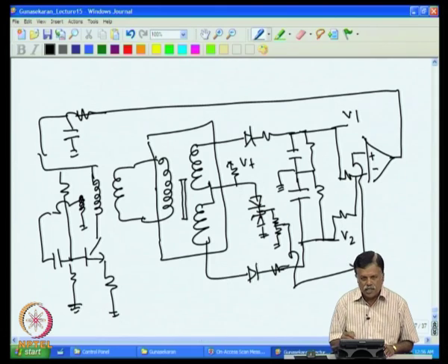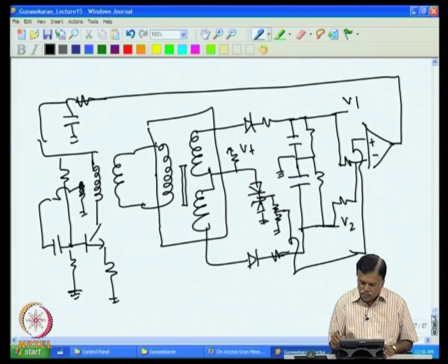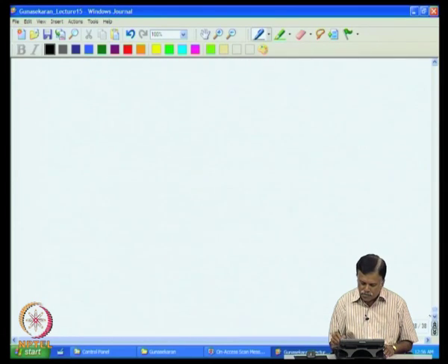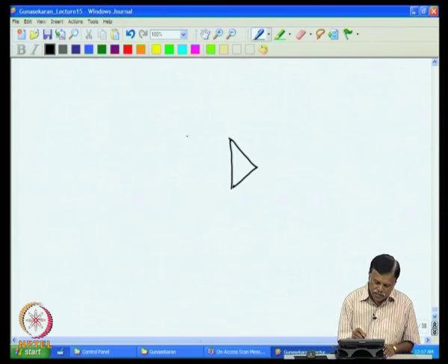the LVDT is to be energized first. Now, the V1 V2 can be utilized to produce a current. Now, that can be done by a simple circuit. What we can do is we can put a current transmitter or even convert a voltage into current. For example, if we have this V1 here and V2 here, we can even put a follower.